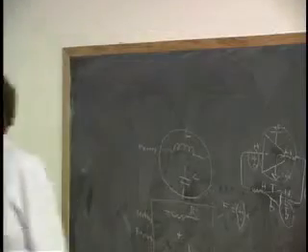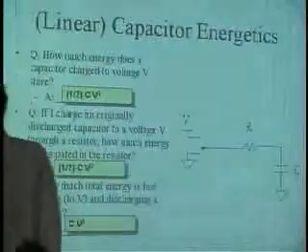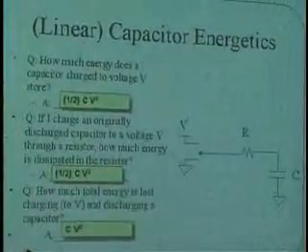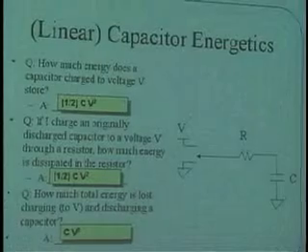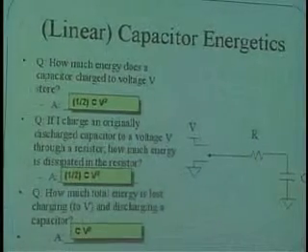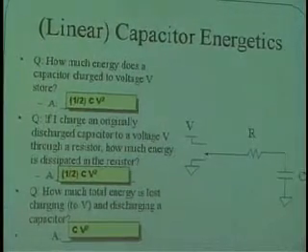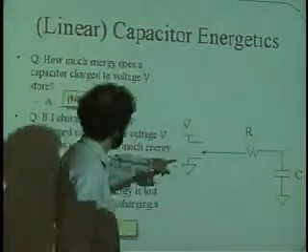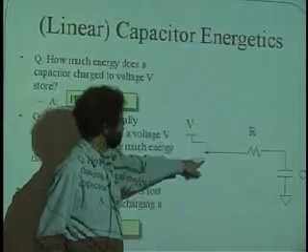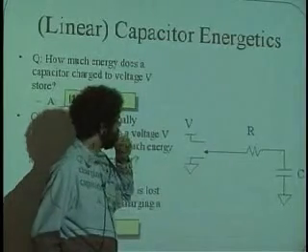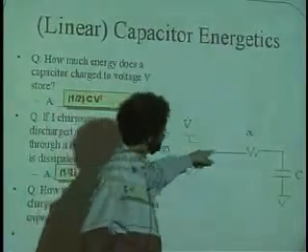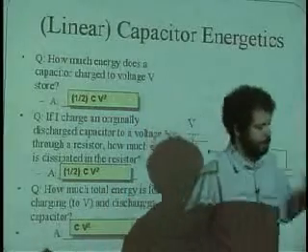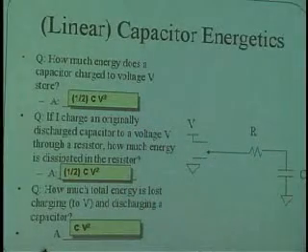Okay. So, you did this in recitation, but let's go over it again. Let's say that we're going to store a bit on a capacitor. And the way we're going to do it is that we're going to switch a switch over here between a high voltage and ground. Well, when we connect it to the high voltage, charge goes into the capacitor and fills it up until the voltage on the capacitor is V.